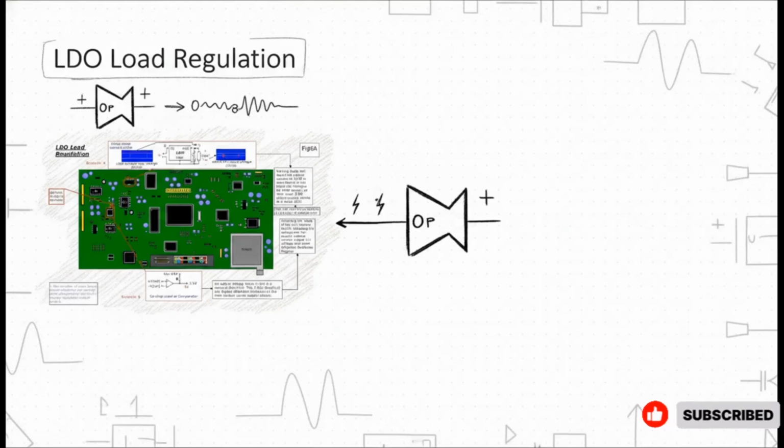To see how this builds, we can look at an operational amplifier, or op-amp for short, used as a comparator for LDO load regulation. Normally, the LDO is in there handling wildly fluctuating electrical loads. We're talking about rapidly stepping between 0 and 200 milliamps just to maintain absolute stability. It acts like a continuous monitor, keeping the intended output voltage perfectly steady, even when the TV's load conditions are varying drastically from moment to moment.